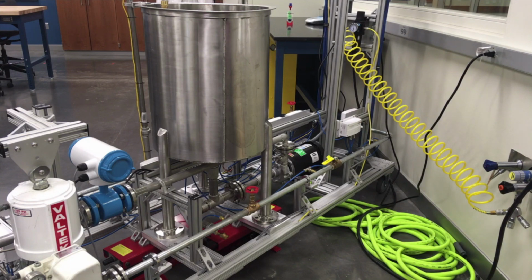Okay, moving on to the pump setup, you can see here on the lower left there's the white control valve, and that's what we have access to through the online interface that we'll use in just a moment. At the bottom center there's a red globe valve, and then a little bit to the right of that on the main flow path there's a yellow ball valve. That loops around to the back where there's another red globe valve that controls the bypass split.